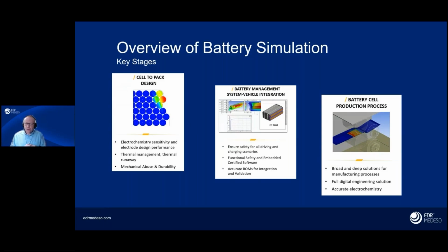So the center top trumps card here was taken from an Ansys example for the automotive industry, but it's applicable in any industry where we're going to consider cell deployment. So we're able to simulate the integration of these cells and their operation within system level models. We can generate a reduced order model from our original analyses that we've done in stage 1 in the cell and pack design. And we can use these reduced order models to almost instantaneously give us feedback and an idea of how our cell is going to behave in the overall system.